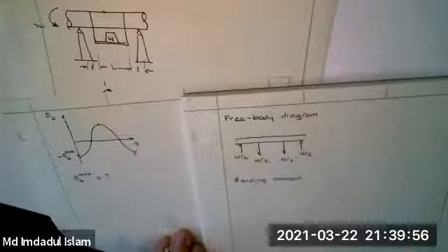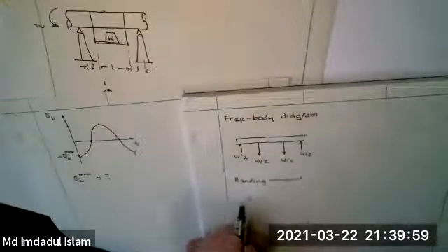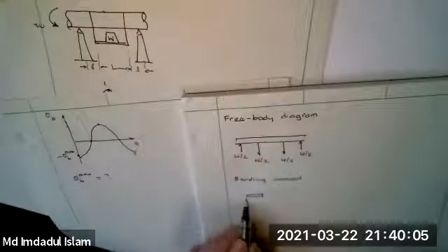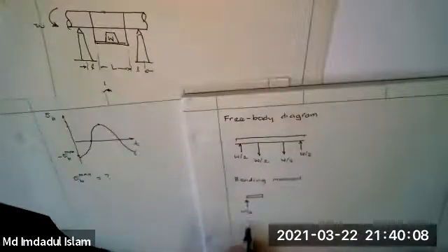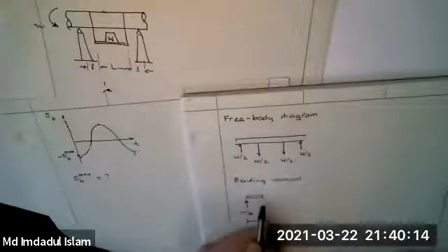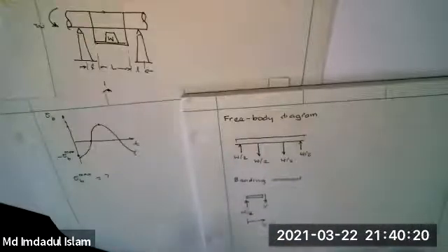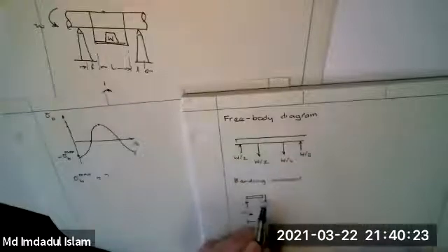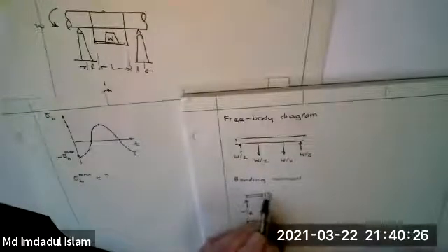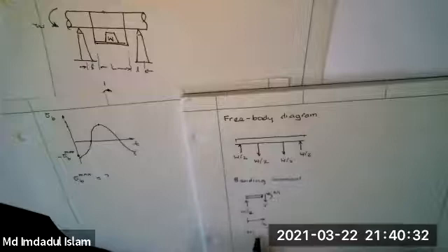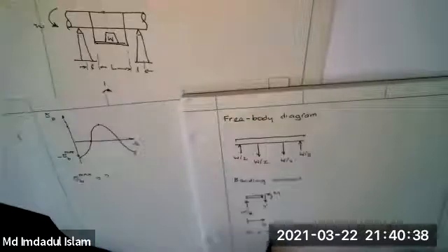Well, it's fairly straightforward. We're going to measure X from that end. Put in the known reaction. Then I put in the shear force, positive, reducing a clockwise movement. It doesn't matter anyway. Then I put the bending moment, compressing the top, the standard convention. If I take moments about here, I get that M, the moment that way, is equal to the moment in the opposite direction, which is W x upon 2.